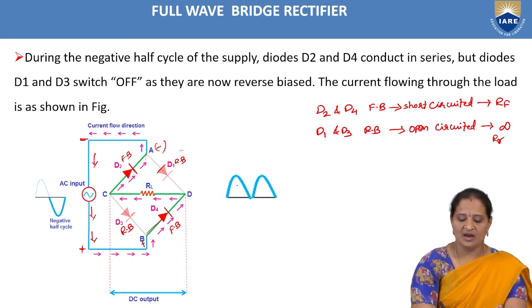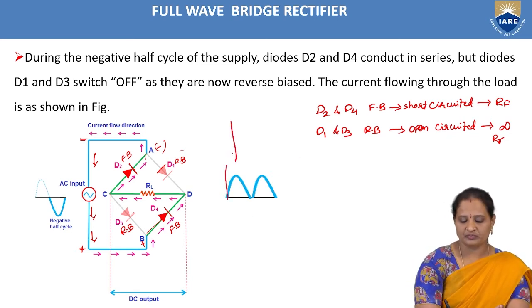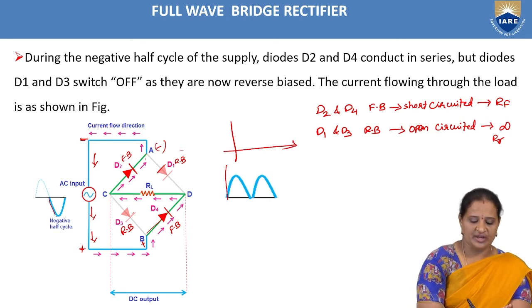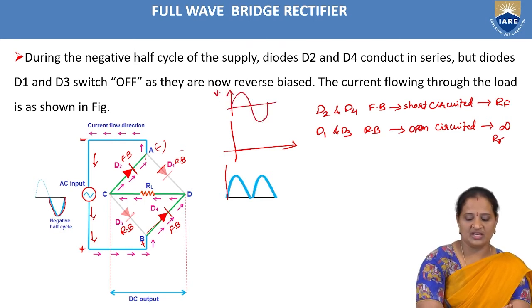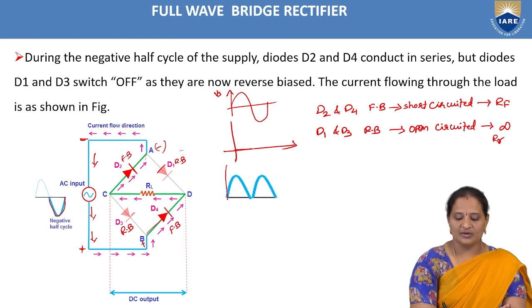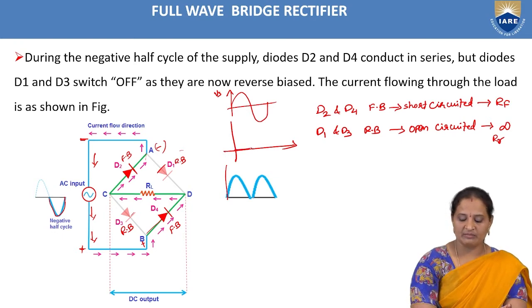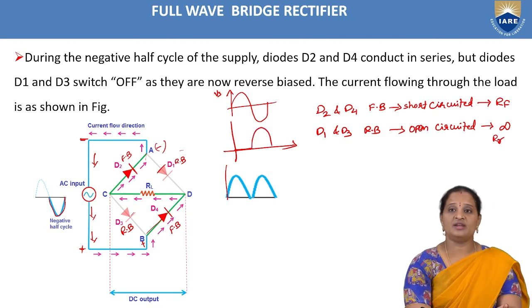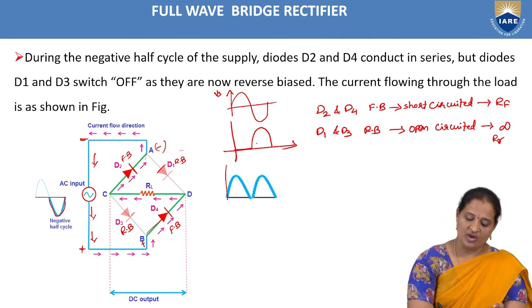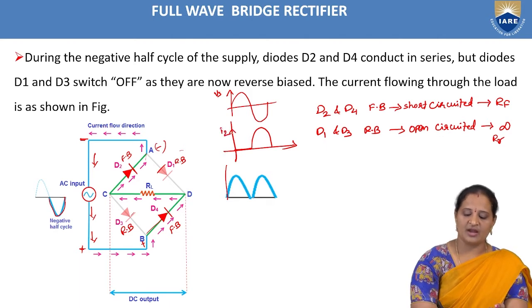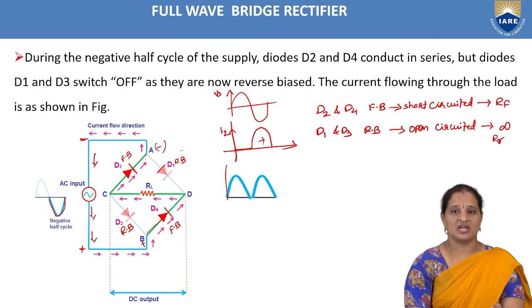So that means here we have I2, which is during the negative half cycle of input. So here this is my input signal. So this is Vs. Okay. And here I'm just considering the negative half cycle. As the current direction is the same in both cases, during positive and negative half cycle, we will also have the current I2 only as a positive half cycle.